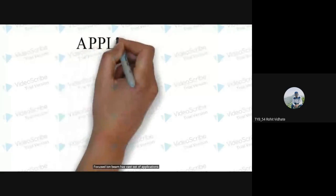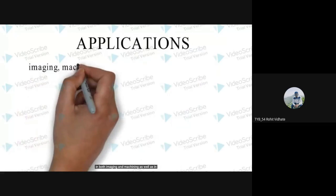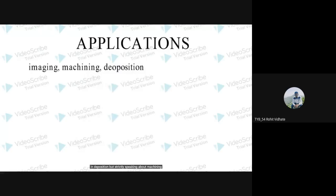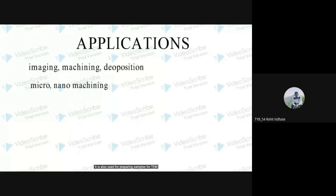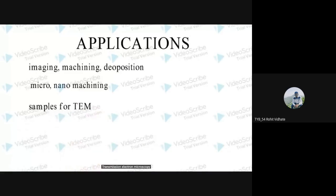Focused ion beam has a vast set of applications in imaging, machining, as well as deposition. But strictly speaking about machining, it can be used for micro and nano machining due to its low material removal rate. It is also used for preparing samples for TEM, transmission electron microscopy, because it can produce ultra thin and uniform lamellae, almost electron transparent for observation under TEM.